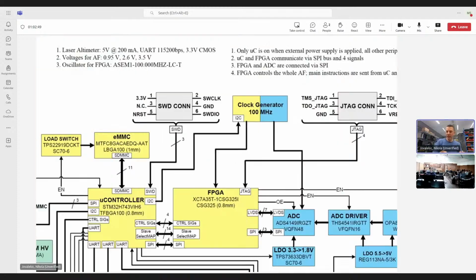If you're in the digital domain, you would always want to put this component, I will just use a laser pointer, this component as close to this component, and you would like to keep this trace as short as possible. That's the general rule, but obviously, different designs dictate different conditions.